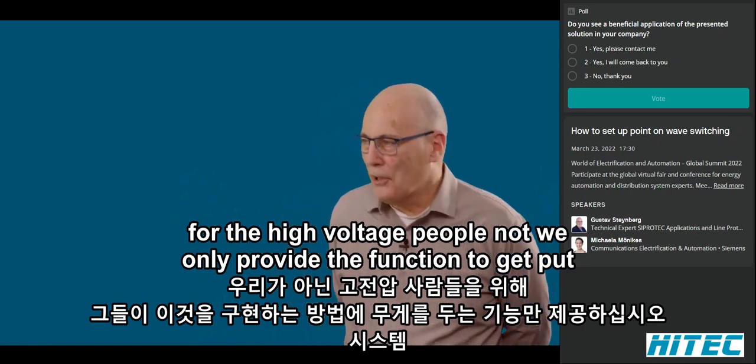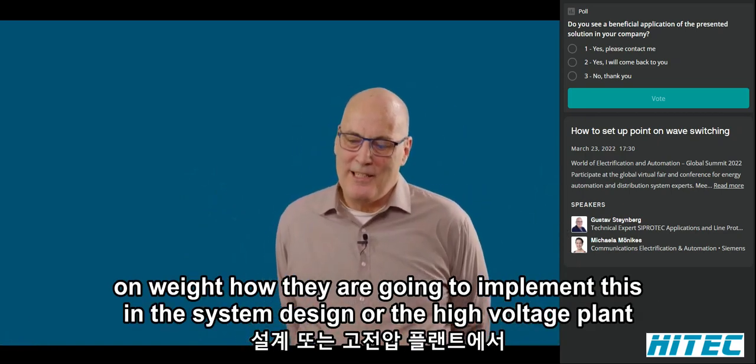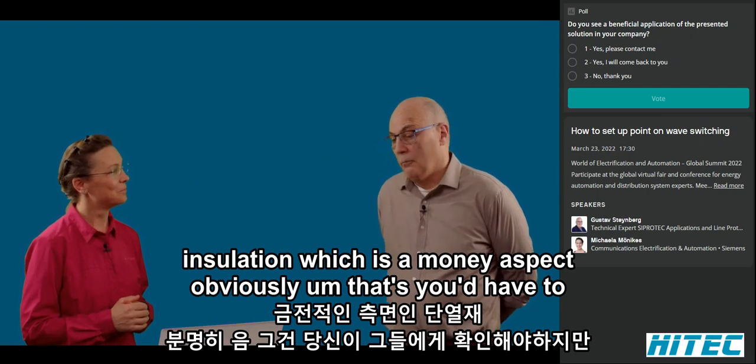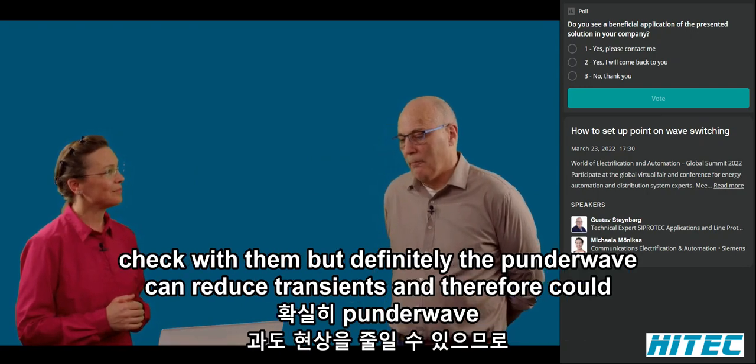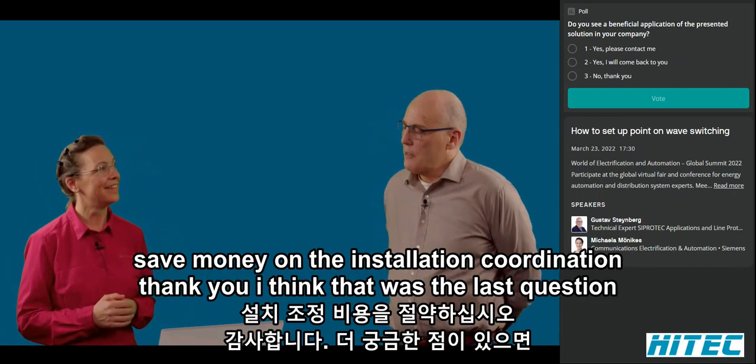But that is for the high voltage people. We only provide the function to do the point-on-wave. How they are going to implement this in their system design or the high voltage plant installation, which is a money aspect, obviously, you'd have to check with them. But definitely point-on-wave can reduce transients and therefore could save money on the insulation coordination.